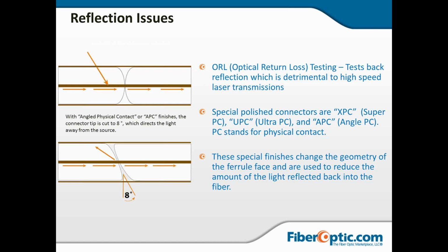We started shooting for loss and looking at optical return loss, started cleaning our connectors, and we had to replace a few patch cords because the connectors were damaged. But we started cleaning up, retested, got our return losses down, and then the technicians started calling us and saying, "What did you guys do?"